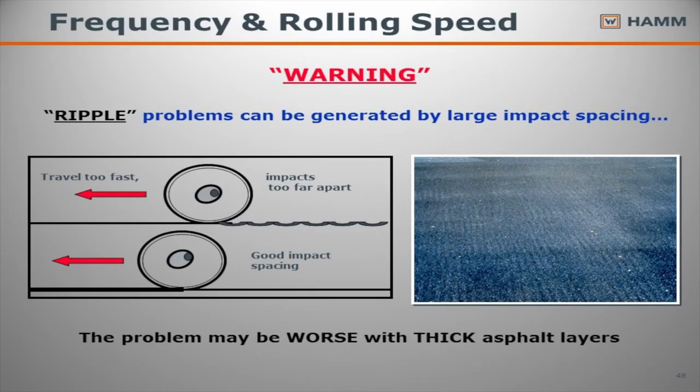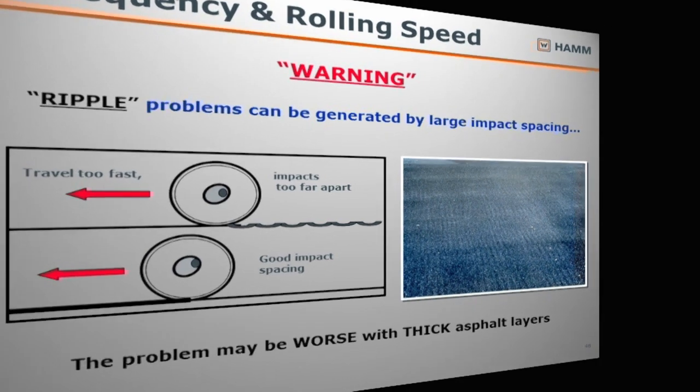Some things too, when you get to a certain point or a certain temperature, and it'll vary depending on the types of mix and the thickness of the mat, we start getting to the point where vibration is going to start either busting rock or creating ripples in the mat. And we're going to feel that in what we're going to do.